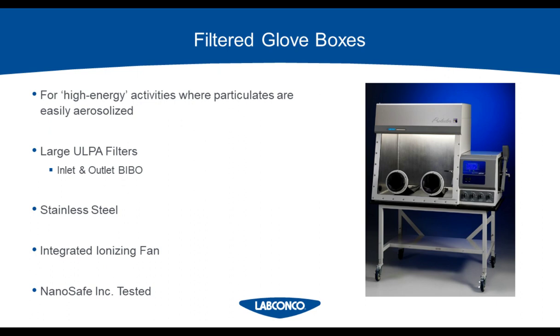ULPA filters, again, with bag-in, bag-out capability, allow you to remove those filters when contaminated, but in a safe manner. Also, stainless steel is really important for cleanability, ensuring that you can get into the corners and crevices of these hoods to clean them. This is a great way to ensure that you don't leave any nanomaterials behind, which can reduce contamination of another experiment, and is also just good practice for cleaning the hood. You can integrate ionizing fans into these types of boxes as well. There are a lot of options out there. Certainly investigate when you're buying the box if you can integrate one into that. But you may also find that you are using a balance that came with an ionizer.